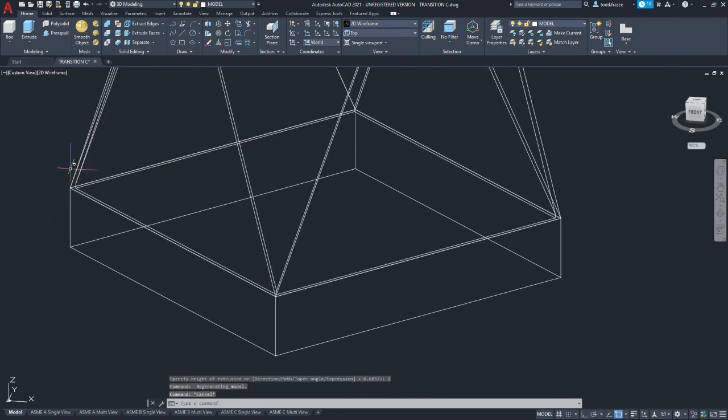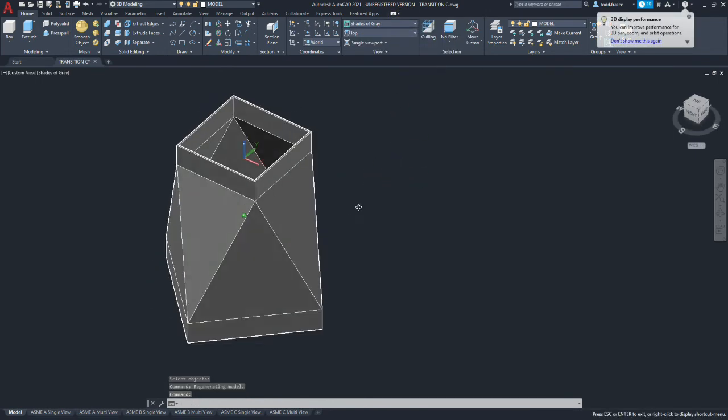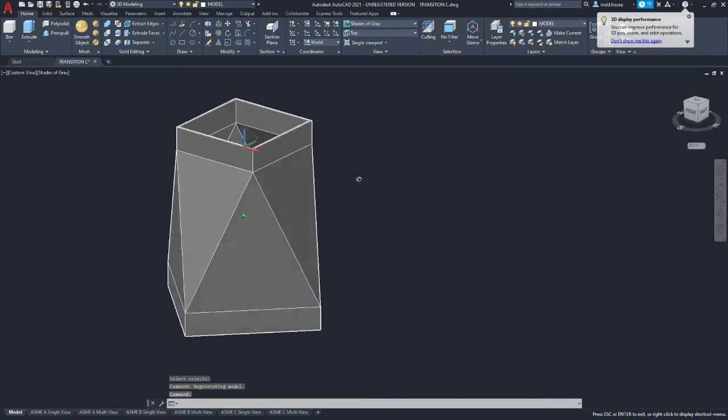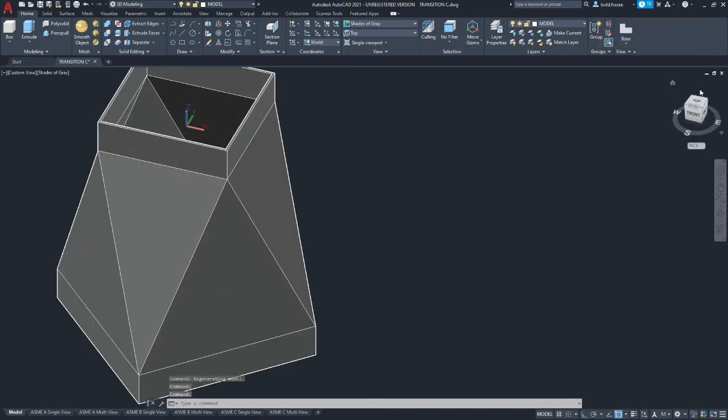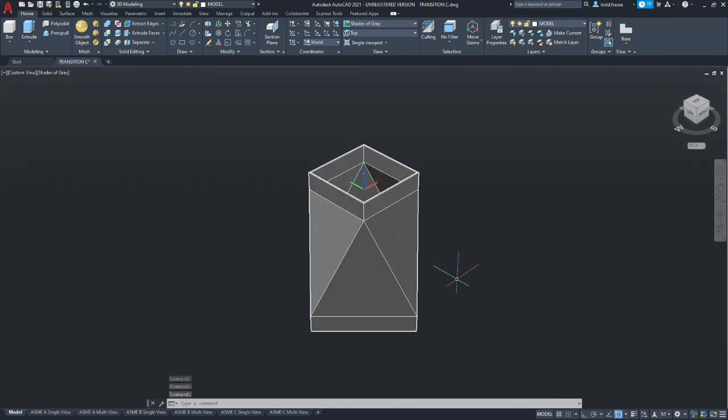Now, because I used the extrude command instead of press pull, I've got to connect the 2 solids and join them into one. Okay, so here we are. We've got our shaded version of the model. And now the last thing we need to do is split this. So I'm going to go back to the home position just to recenter the view. And I think we're going to split this one on a plane across the center here. Actually, we're going to split it this way.